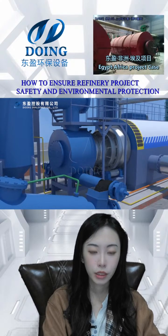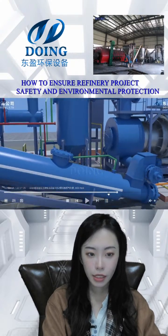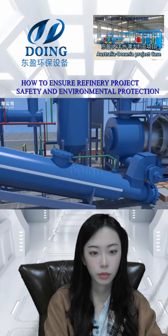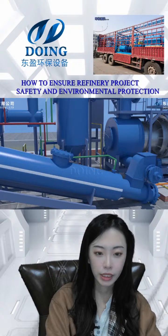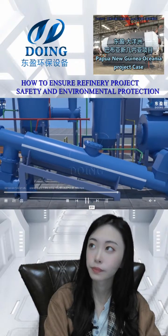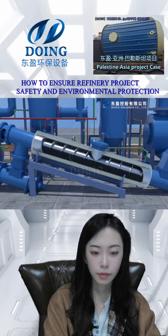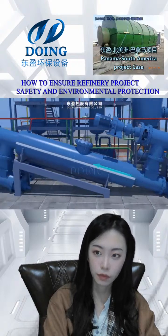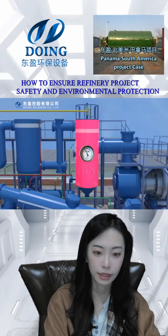And then let's come to the bagging discharging system. This is the first action we need. Here is the heat preservation. We specially designed a material sealed design to prevent the air from entering and the oil gas from leaking. And then by using 3 stages of the same design angle with the cooling water cover, the carbon black will come to a normal temperature, then we can just pack it directly.